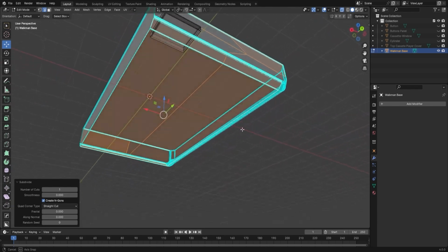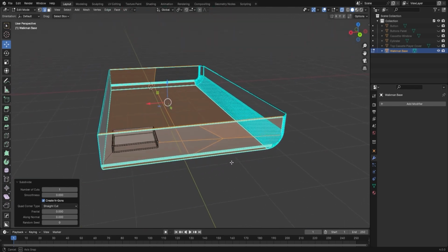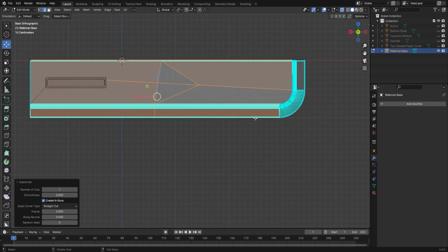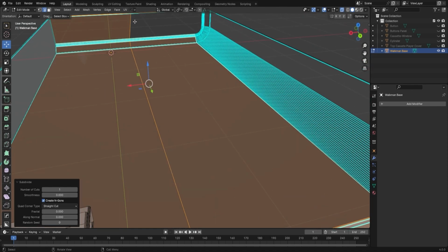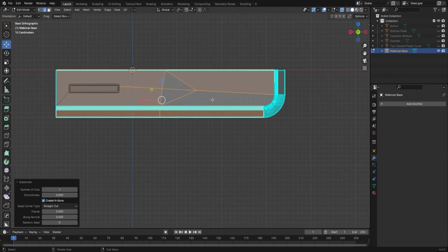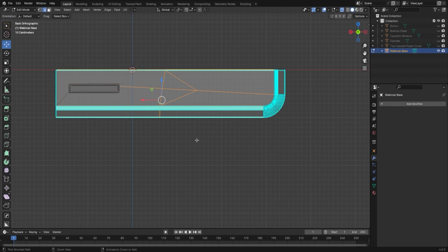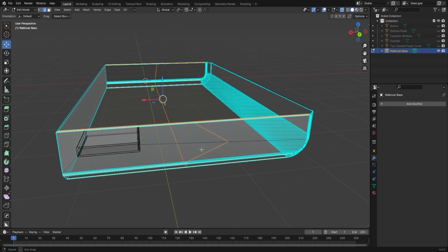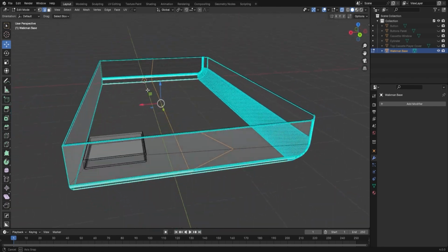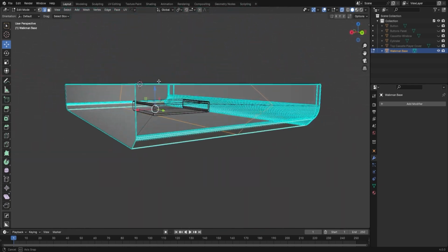Okay, so this is what we are getting, but this is not straight. So what I'm going to do here is that once I have this, I will make sure only this straight line from here till here is selected. So I will deselect whatever I don't want. So I will press Control, select the segments that I don't want. I don't want this segment. I don't want this segment. Okay. And I don't want this part here as well. I don't want this. And yeah, that's all what I need.